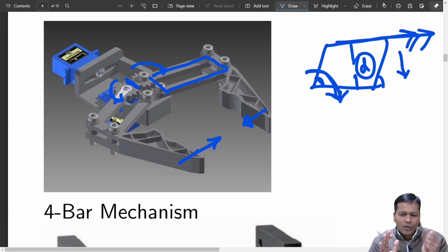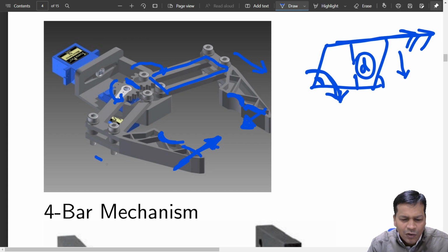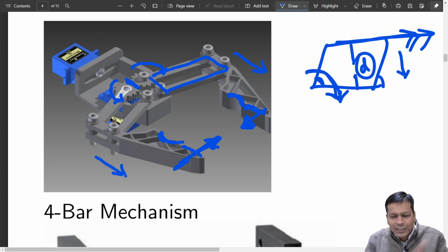So yes, this type of arm is very simple. It can apply quite a good amount of gripping force. The only problem that I see here is, yes, you have a circular surface at both the ends, so that it can grasp something which is cylindrical. If not, then it is rubber padded also, you can hold any diameter object, it won't slip. But yes, apart from moving the jaws like this, it is also traveling in this direction. That is not always desired. It is very difficult to estimate where you are going to end up. Okay, it has a probability to hit the target, right?